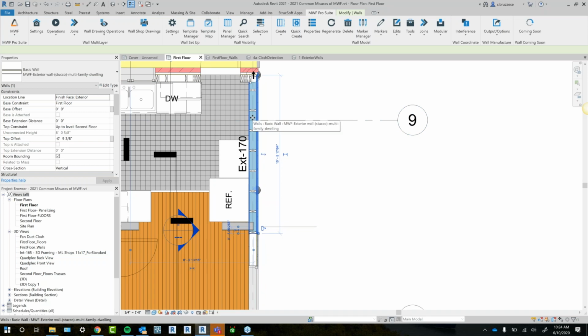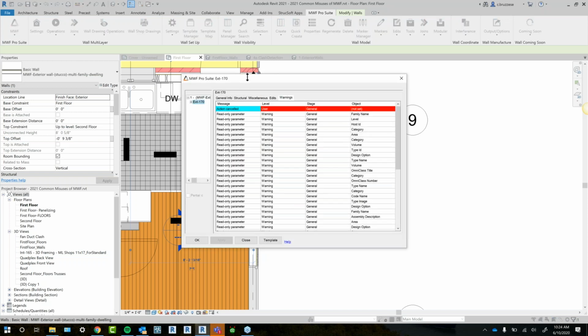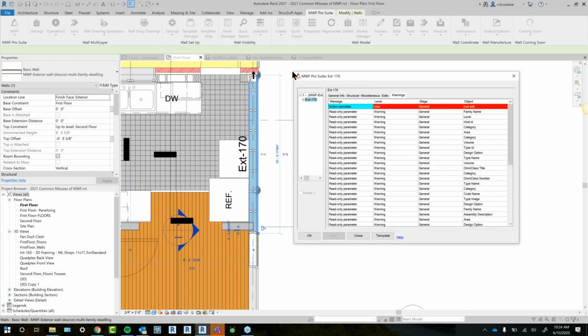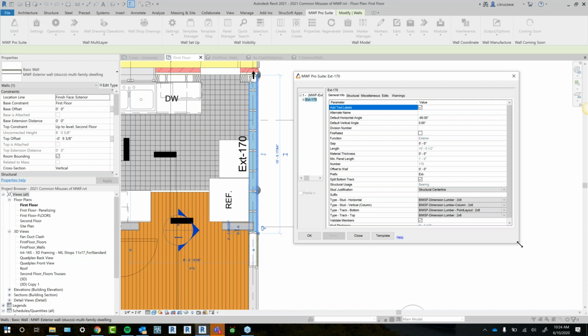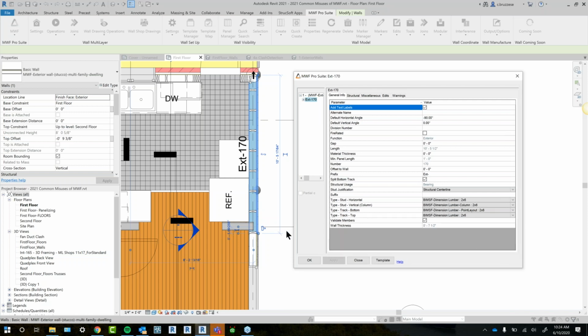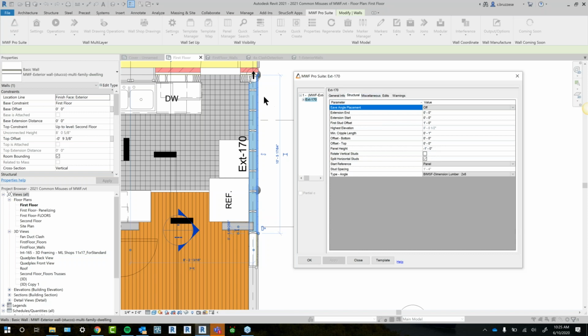All right. So a few other general tips for MWF, for templates. Something I'll also see time and time again is if you are maybe framing and saving templates as you go along, just make sure that you do save a template on a wall that has no connections. So the reason for that is we can see here that I do have a join on this wall.